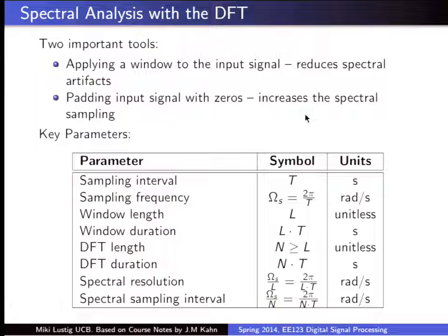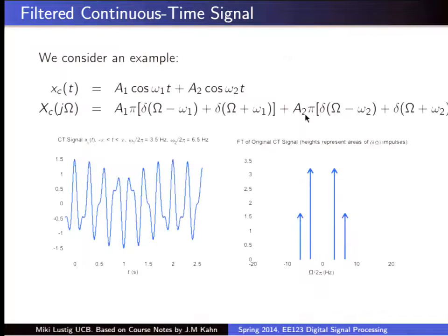And I kind of showed it to you when I used a smaller size window, everything looked a little bit rounder. All the peaks that were sharp in the large window became rounder and more spread out when I used a smaller window. But when I displayed it, I actually interpolated it. And interpolating is what zero padding means. And you'll see that. So here are some examples.